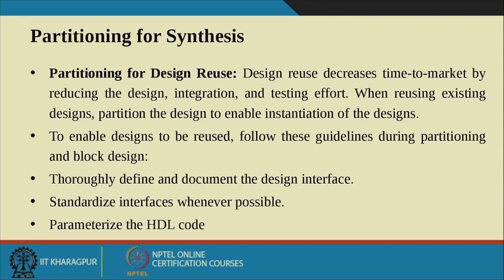So here what you can do is reuse those designs for other designs. In Design Compiler, that option is there. To enable the design to be reused, follow these guidelines during the partition and block design. Thoroughly define and document the design interface, standardize the interface whenever possible, parameterize the HDL code.